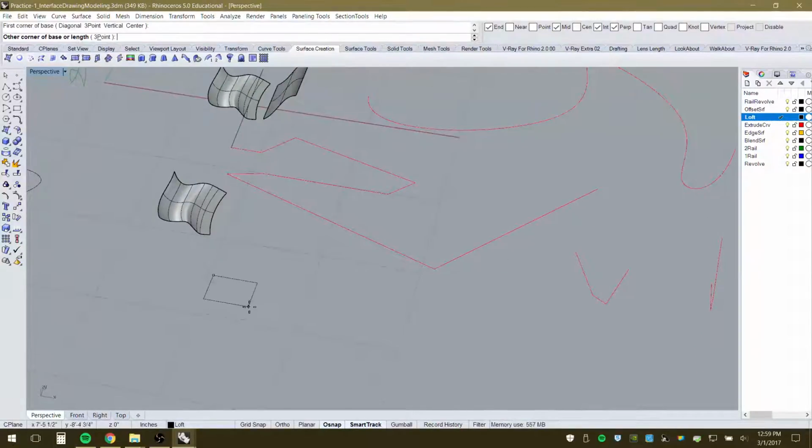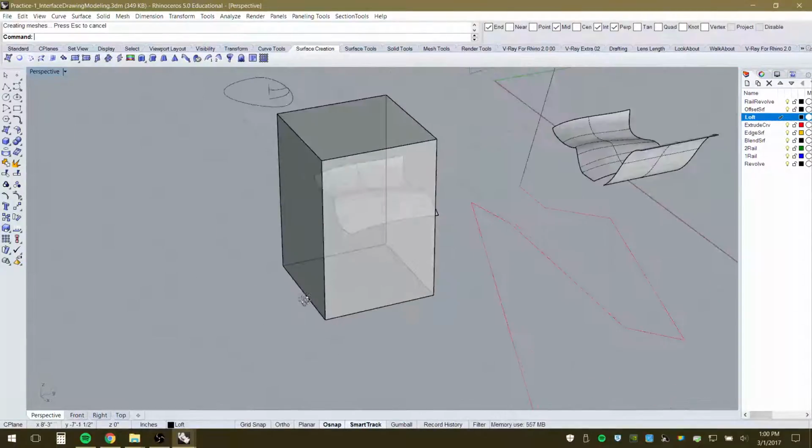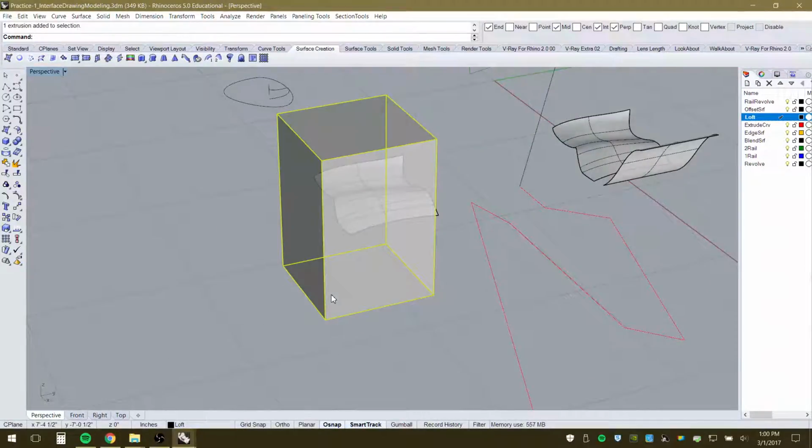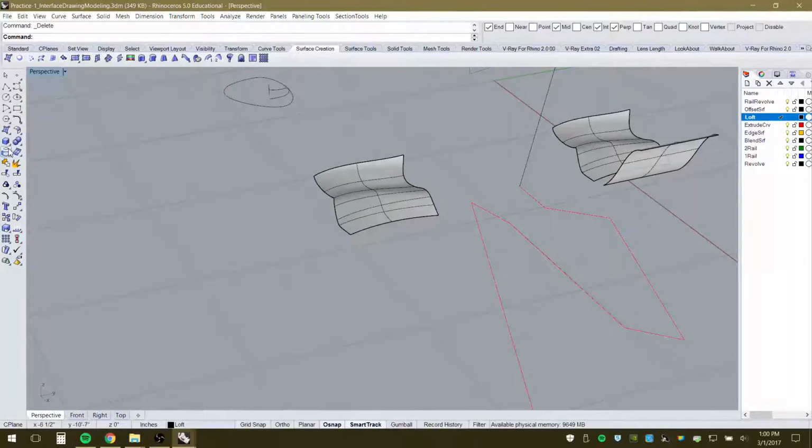box. So I selected a point, and I could simply select at, say, 24, 24 inches. And now it wants a height, and I can select 36 inches. I'm just typing this in. And that's so I can be really precise with the kind of block or box that I create. There are others in here, cylinders, spheres, all these other things. I don't tend to use these a whole lot. Even the box I don't really use very much.